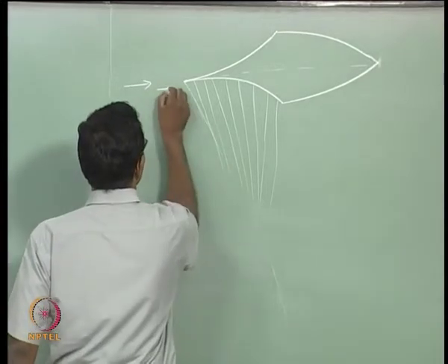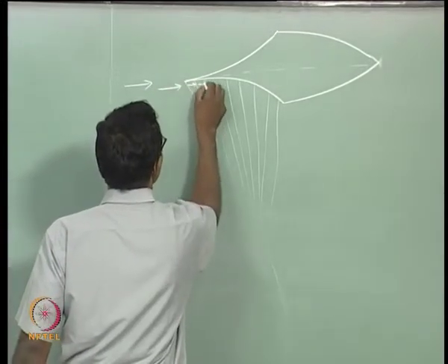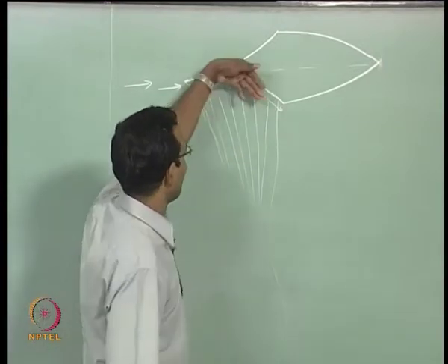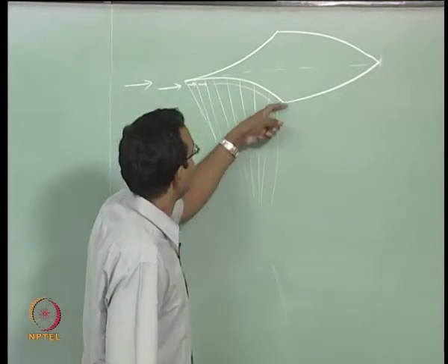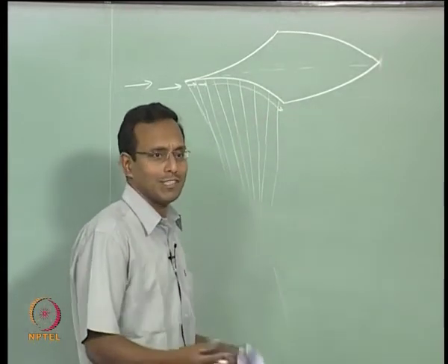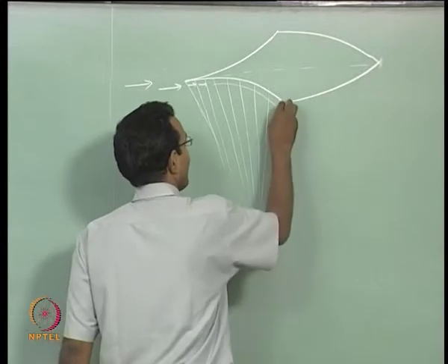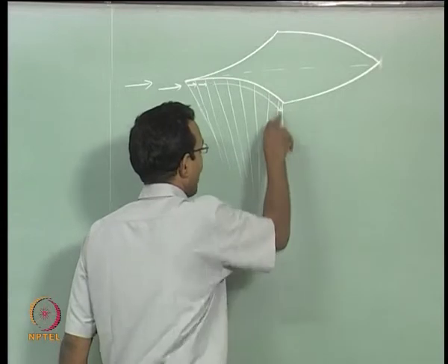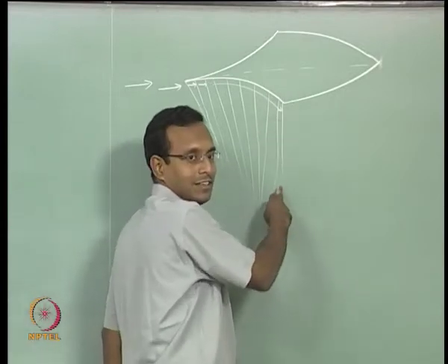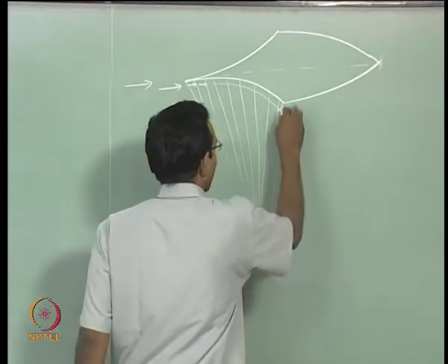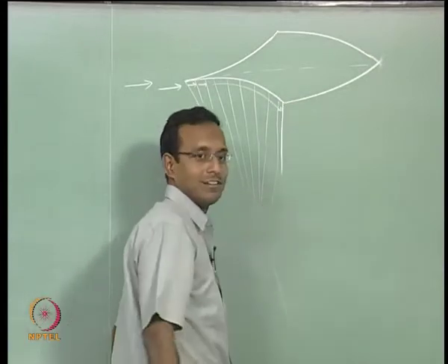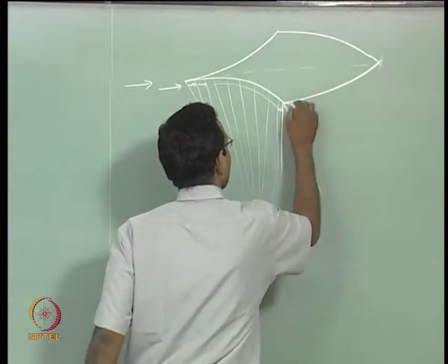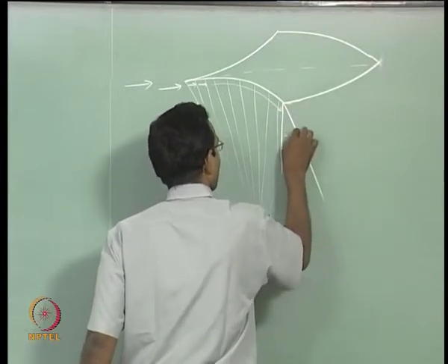So, what is going to happen is the flow is coming here and it is slowly turning there along the wall all the way, and it is going to come to this point, and it is coming out at some high angle this way. Immediately I am telling it is going to 0 angle there. What is that? That is an expansion fan. Okay. And we know that the last compression wave there is also a Mach wave, which means my expansion starts immediately there, and this whole region will be my expansion fan.